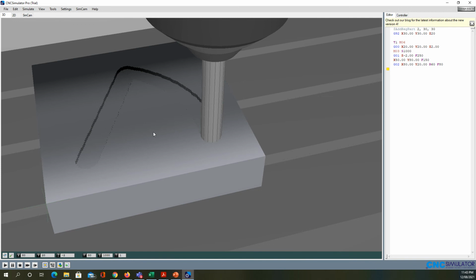And I will give you another one. I'm going to make a hole here, then go to the left and try to make an enlargement for the pocketing here. So I'm going to send the cutting tool up with G00 Z equal to 2.